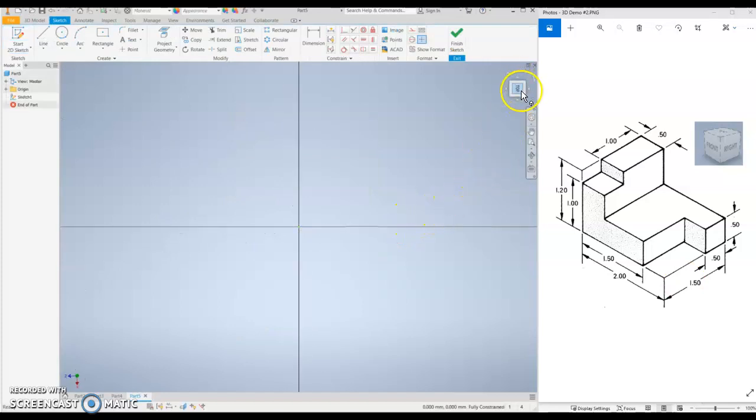All right. Now, when we look at our shape here, you can see that the word top is tilted on us. It's like we're standing here, but our head is over at this end here. If we want it to be more of a front view, we can rotate our view, and it's indicated by this box here. There are these two rotational arrows here. Let's take the top one to spin it left, and now we've rotated so we're looking down. So we're standing at the front of our object, but we're looking down on top of it.